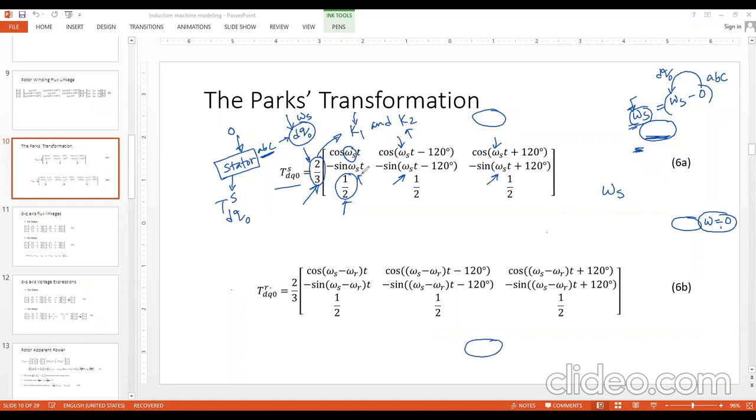Now, in the case of the synchronous machine, we only had two speeds. The rotor itself, in steady state, this was the rotor, this was the coil, and this was the d-axis. The rotor as well as the d-axis were both moving at synchronous speed because it was a synchronous machine. So under steady state, both of their speeds were omega s. Stator speed was 0. So there were only two speeds involved in the case of the synchronous machine, the synchronous generator, let's say.